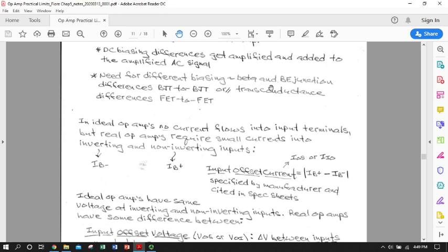Because let's face it, the manufacturers have tested this. They have an idea of what the range of quality control is, and therefore what the range of symmetry of the diff amp portion of various amplifiers is, and so they capture a lot of that in the spec sheet. So this will give us an idea of how to take those listed input offset non-idealities in your spec sheet and translate that into how bad my output voltage signal is going to be.